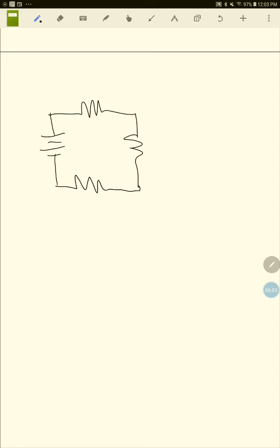Now, the last thing that I want to review in this series circuit is shorts and opens, because series circuits can go bad. And so if you had a series circuit that was working normally, and let's say that we had 12 volts over here, and we'll just make these equal to make it even. So this would be 4 volts, 4 volts, and 4 volts. And so this circuit's working along normally. And all of a sudden, one of these resistors, maybe it overheats or whatever, the lead breaks off of it, and it opens. What's going to happen to the circuit?